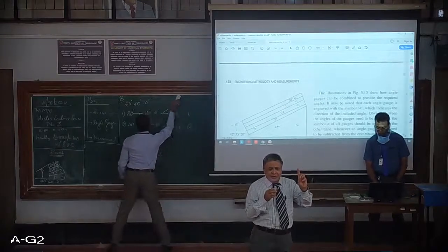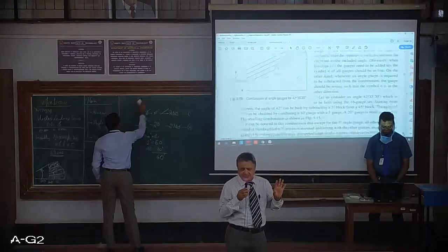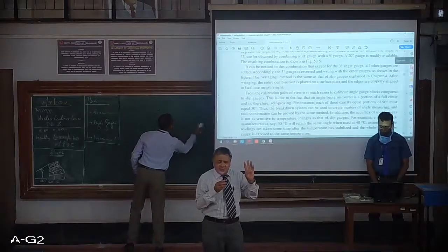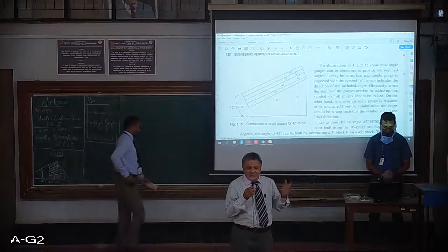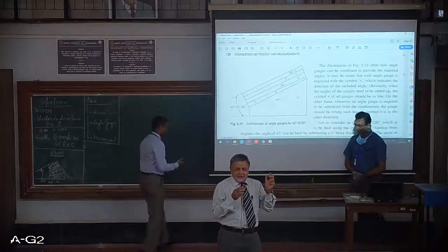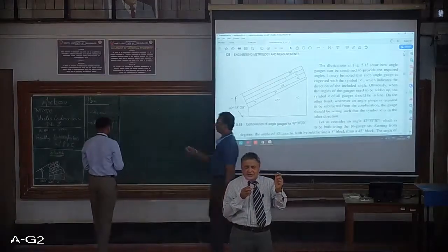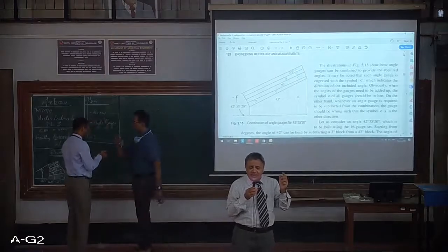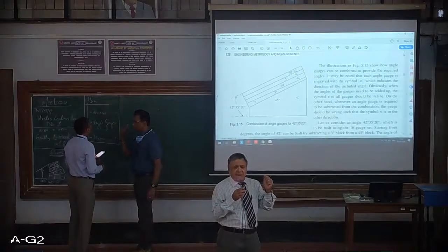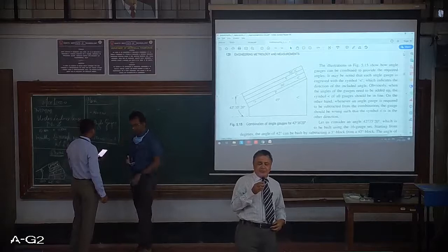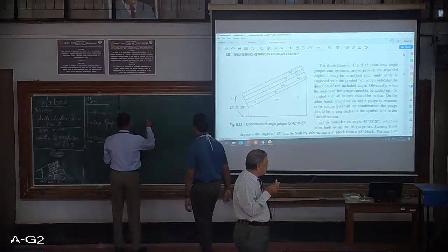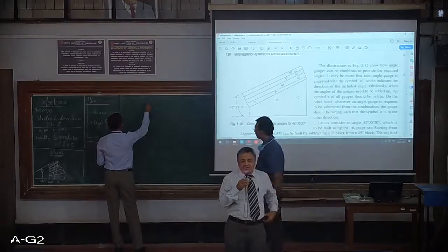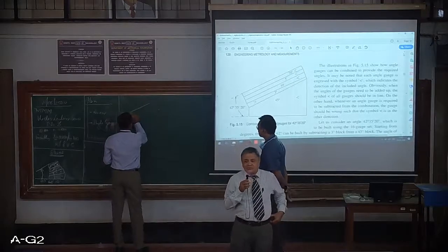It is like degrees 1, 3, 9, 27, 41. Again I repeat, degrees 1, 3, 9, 27, 41. There are 5 sets. Then minutes 3, 9, 27, 41. Then seconds 3, 18, 30 and 45. So there are 5 plus 4 plus 4, that is 13 angle gauges.